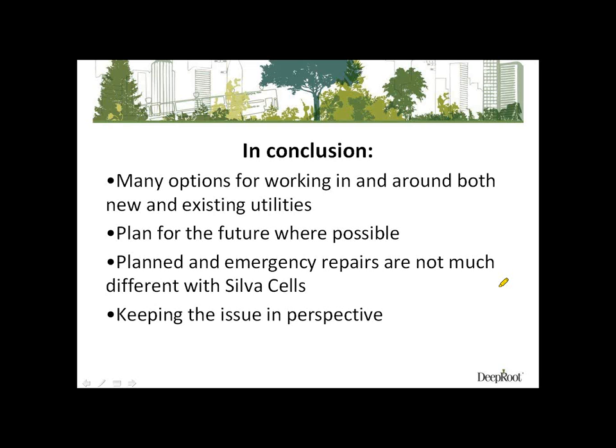I'm pretty sure that they're talking about when you use the aggregate gap detail, or when you're filling an area inside where you're leaving out cells, and that rock. That's why we always line the inside of the opening with geogrid, so that the geogrid restrains the rock and keeps it from pushing into the soil. Because yes, the person who sent the question is absolutely right. Over time, there would be a tendency for that rock to migrate into the softer soils around it.